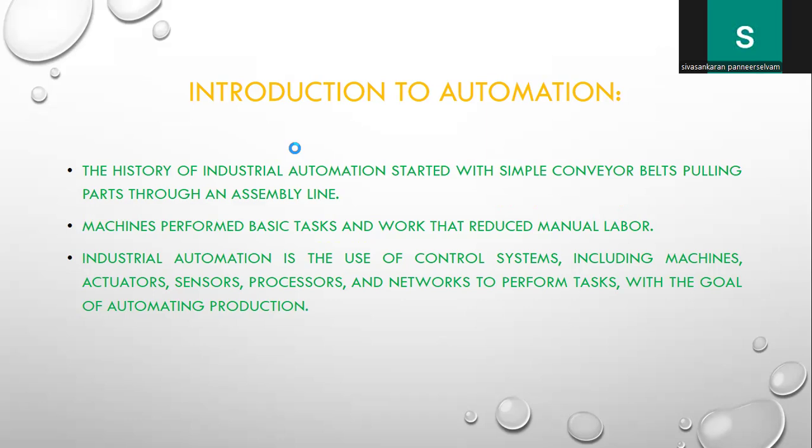The main function of the conveyor is to move the mechanical physical parts with the help of a belt pulley mechanism in order to feed each and every part forward into the corresponding assembly workstations. So that reduces the manual labor cost by automatically feeding the parts to every assembly station.